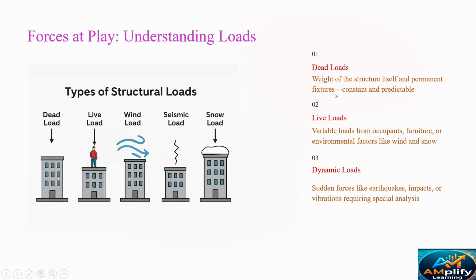What is dead load? Whatever material is used, and whichever section is used in the structure, has a weight. This load is called the dead load. It does not include any live load, snow load, or wind load.